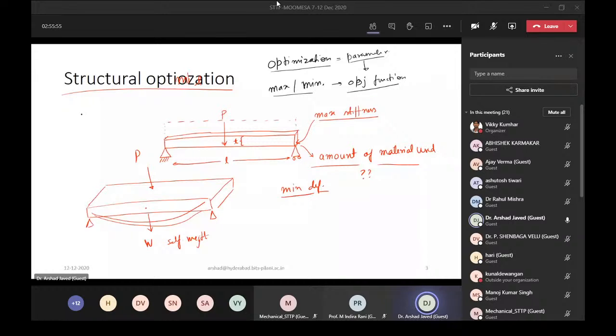For example, you wanted to increase the heat transfer from a cylinder. The surface to volume effect is going to come. So you wanted to dissipate heat from a heated object which is in cylindrical condition. We wanted to dissipate more heat from this one. So we need to find out what should be the volume and what should be the surface area. The mass is going to be fixed. So the parameters in this problem will be to find the values of H and D, correct?